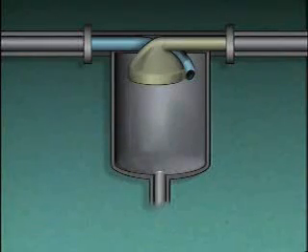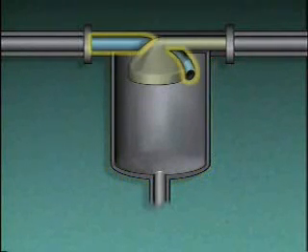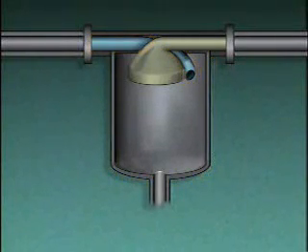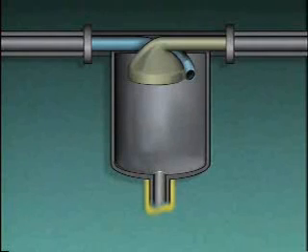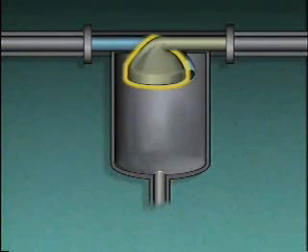Air and other gases generally contain some moisture vapor. When gases are compressed and then cooled, the vapor often condenses into liquid droplets that can damage some types of pneumatic equipment. To prevent this from happening, moisture separators or demisters are often used to remove these droplets. This illustration of a demister includes a shell, a gas inlet line, a liquid outlet line, and a gas collector, which is connected to a gas outlet line.